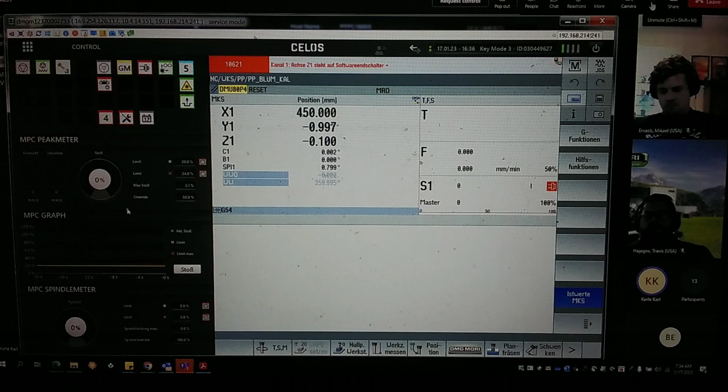We have a percussion, a vibration sensor installed in the main spindle, and this sensor is measuring the intensity of the percussions, so this is a reference value to know if the tool in the spindle is working well, or maybe one or two of the cutter edges are broken, or the abrasion of the tool cutter edges is too high, so you have more and more vibrations or higher intensity of vibration like that. And this could be indicated by this graph.